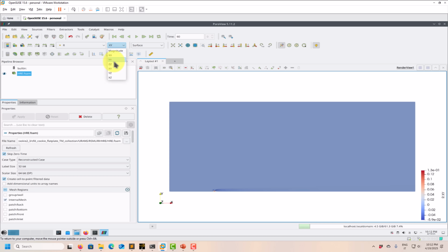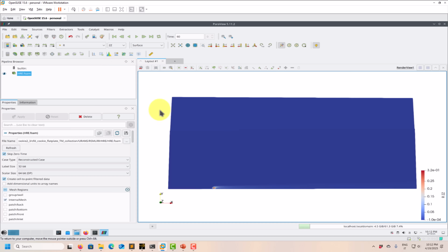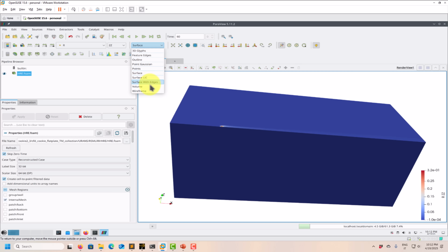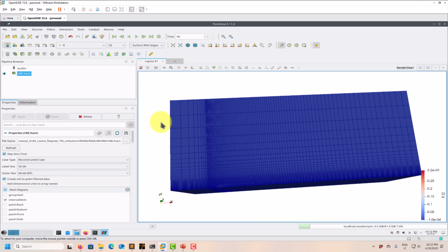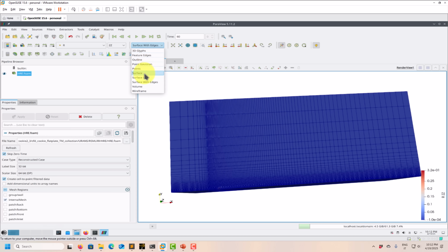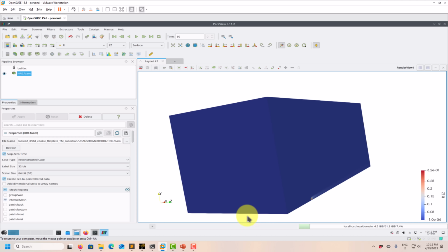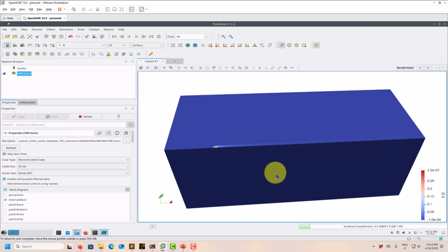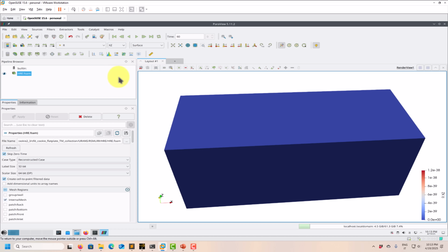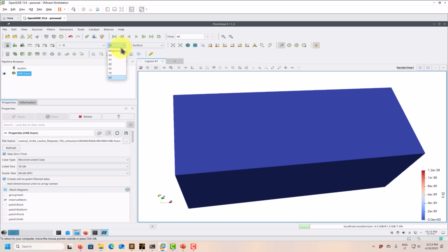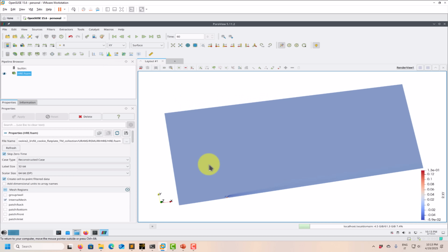Very interesting, this model. So recall that. Let me rotate. Let me put the mesh. It's a 2D mesh. Remember that this case is 2D. For some reason, this model is computing in Z. Look at that, Z is this one. We shouldn't have anything in Z because it's 2D. And look at that, you have this. So it's a source of error that you need to monitor, be careful about that. This is very strange. I don't recall, I think somewhere there is an explanation for what is happening. It might be a bug, it might not. Okay, but be careful about that.